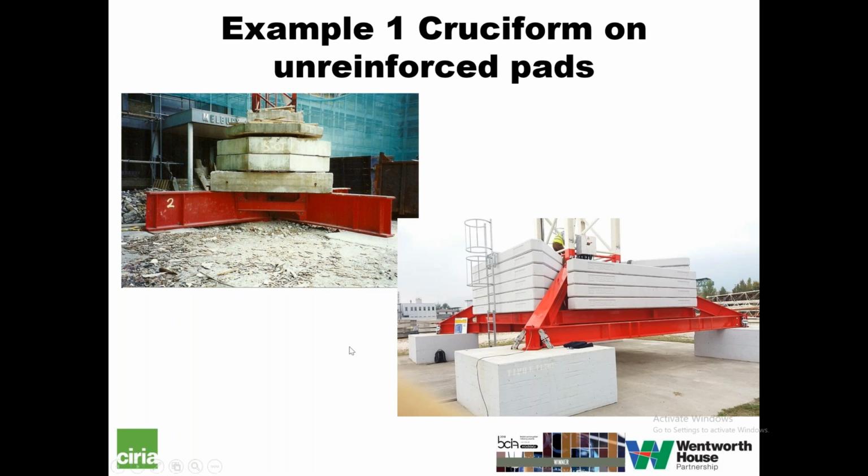You can see in the bottom right-hand corner picture, there are some restraints to that grillage there. The restraints should allow vertical movement because the grillage is not designed for being held down at that particular location, unless the manufacturer has been consulted and that is the design case. Normally the kentledge on the crane is sufficient to hold it down.